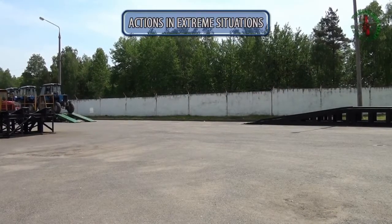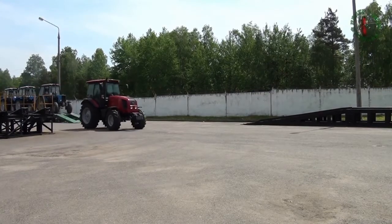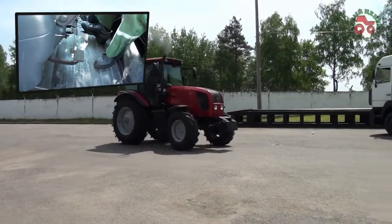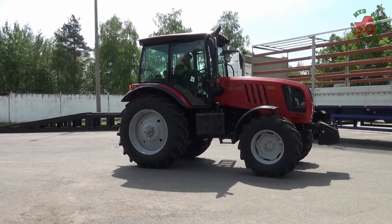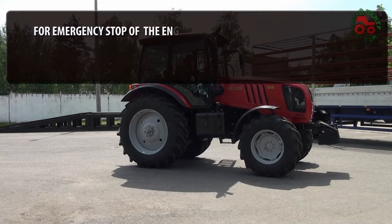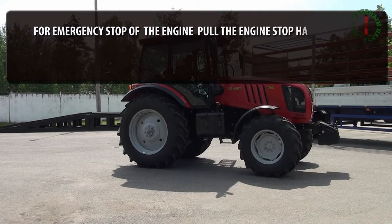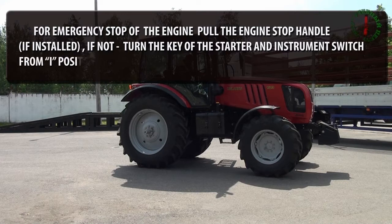Actions in extreme situations. To stop the tractor immediately, sharply depress the clutch and brake pedals. For emergency stop of the engine, pull the engine stop handle if installed. If not, turn the key of the starter and instrument switch from position 1 to position O.